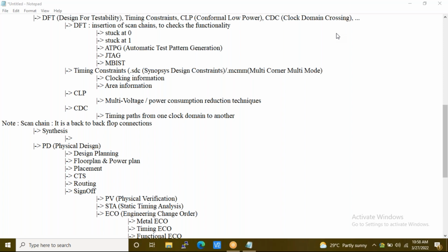Whenever a signal moves from one clock domain to another clock domain, it leads to metastability. Metastability means something wrong can happen. It may become good, it may become bad. Now in the bus example, what will you do to avoid metastability? To avoid falling down, can someone tell me? Let's say you still want to catch a running bus. You are walking. What will you do to catch the bus? We need to match the speed of the bus.